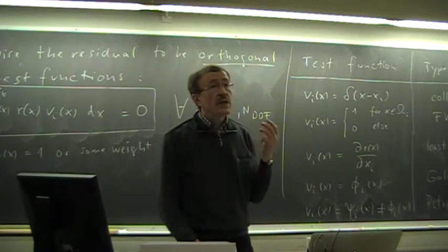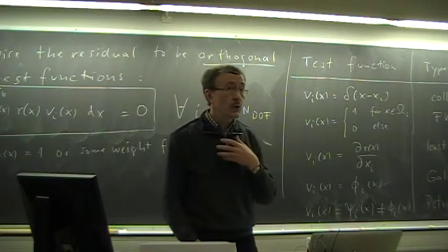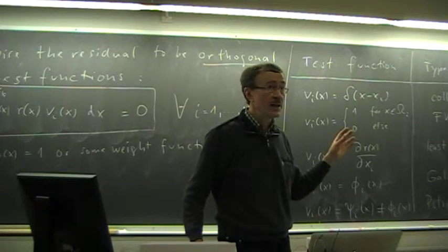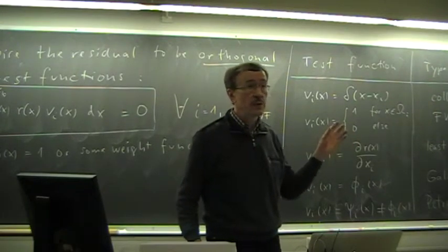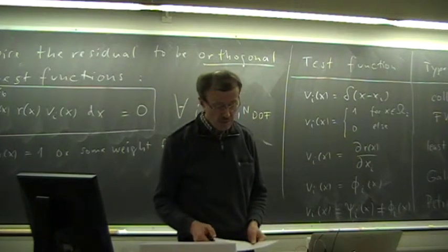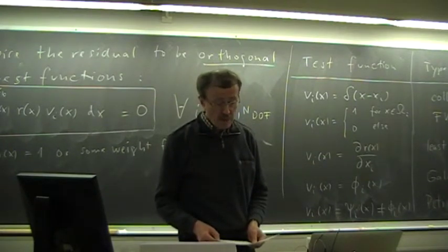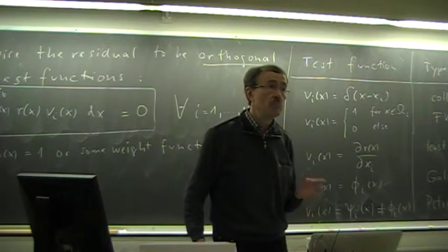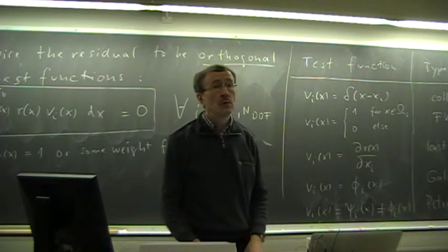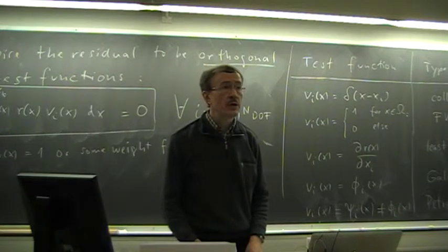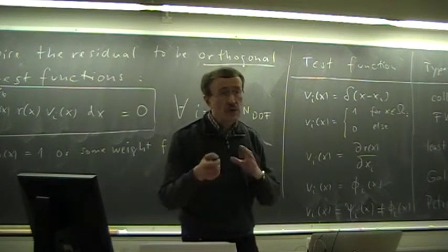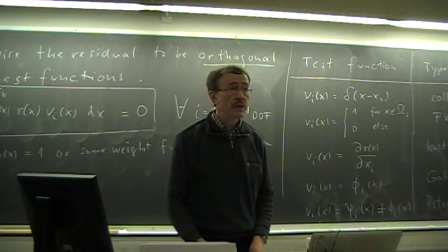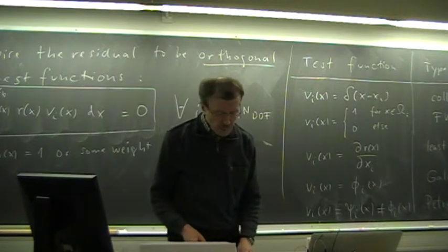The finite volume method has its strength in that it does the conservation laws as they should be done. It is the integral form just as we learned in fluid mechanics. So that is the strength. That is probably why it is mostly used in CFD. The spectral method is extremely accurate, so if you have problems with simple geometry and simple boundary conditions, then use it. It is used a lot for fundamental research like direct numerical simulation of turbulence. And the spectral element method is a bridge between that very accurate method and the more flexible finite element method.